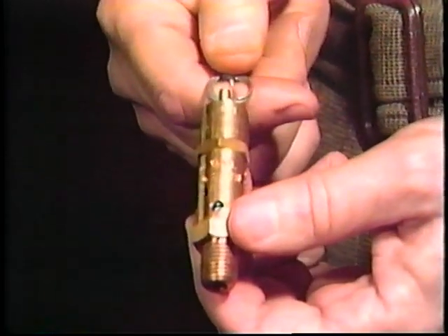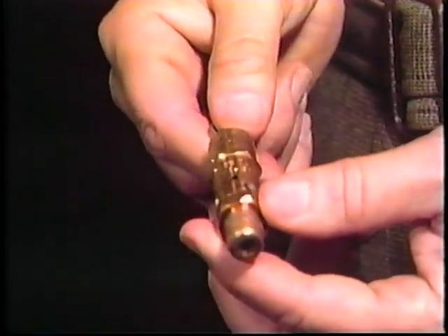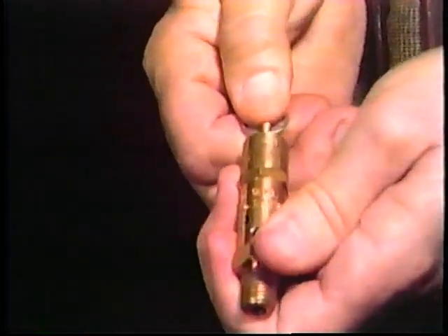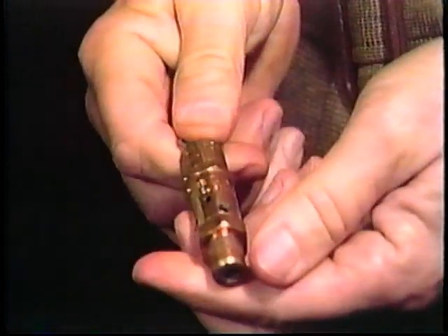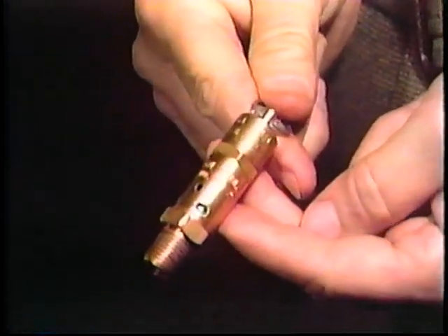Okay, 2 more things before we leave boosters. First, the fluid in the output side of a booster doesn't have to be air. Sometimes oil is used in what is called an air-to-oil system. It operates on the same principles as an air-to-air system, and your text provides some examples of particular circuits. Second, a safety precaution. You should always have a pressure relief valve on the high-pressure side of a booster to be sure that the pressure is not intensified to a dangerous level.